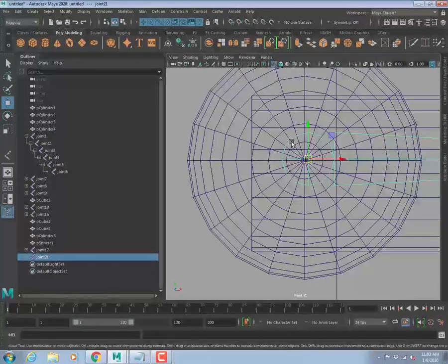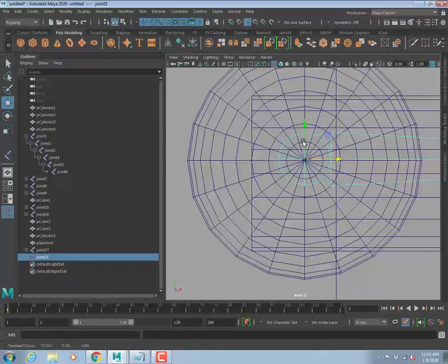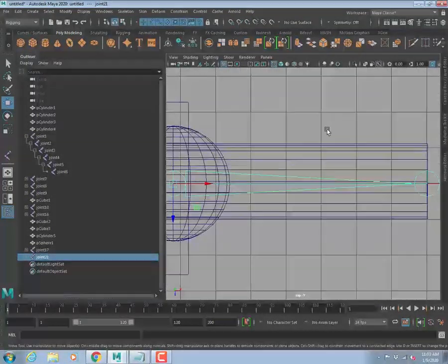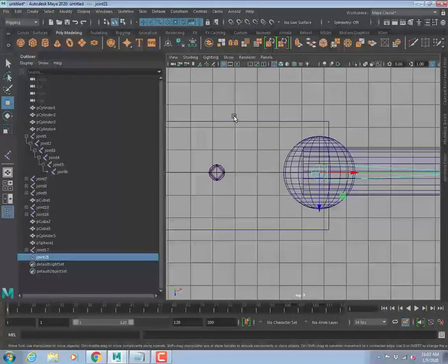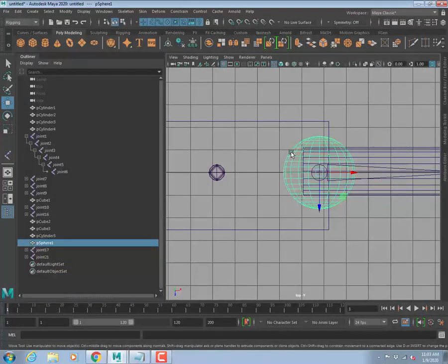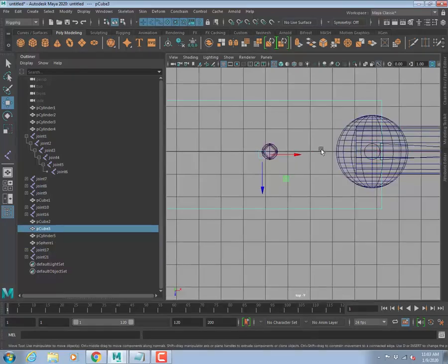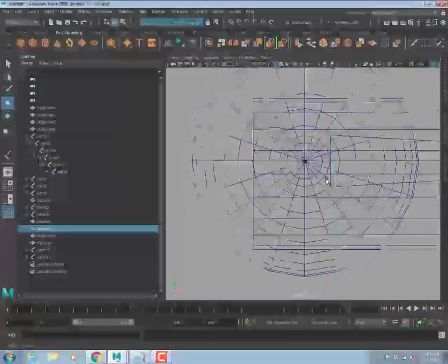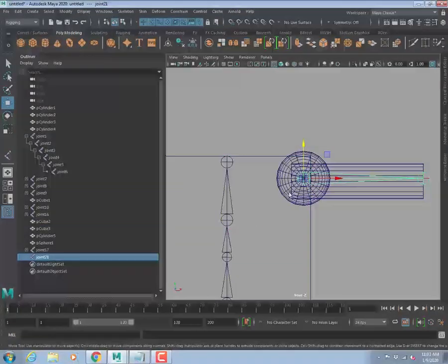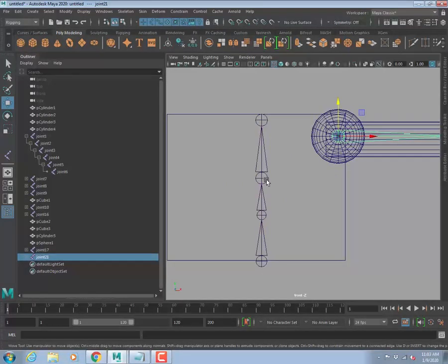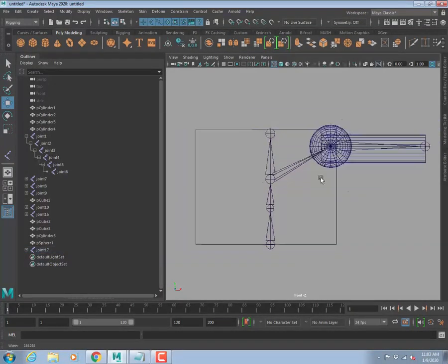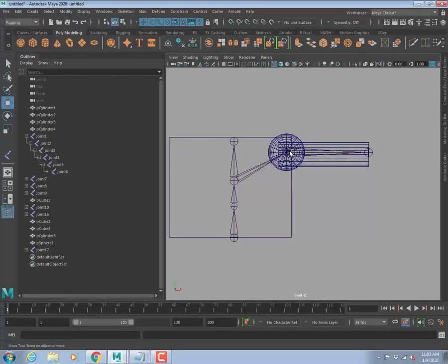So move the joint, press B, click and drag, check from the top view. It is in the center, fine. Check the object, yes. So this is okay. What I do is parent this joint to whatever joint is over here. Shift click, press P. Parent. Now I can actually rotate this joint.